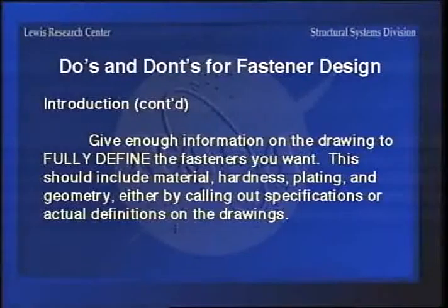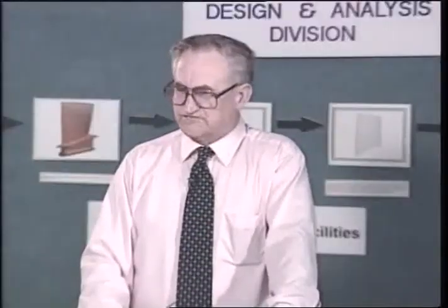For example, on drawings, on materials, I know I have seen on drawings where it is critical enough that you even specify the grain direction on the drawing. Because, you know, on materials, you have a longitudinal, transverse, and short transverse direction. The short transverse is usually the weak one.